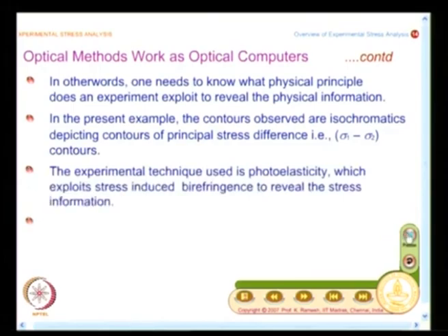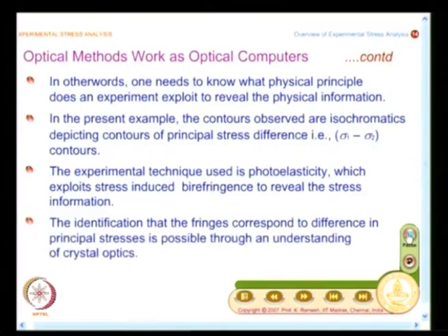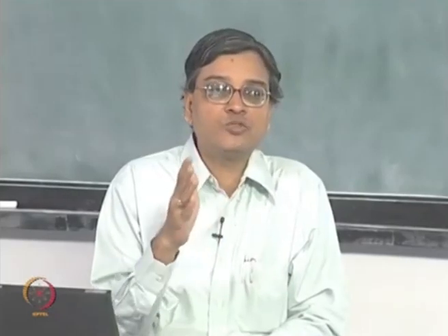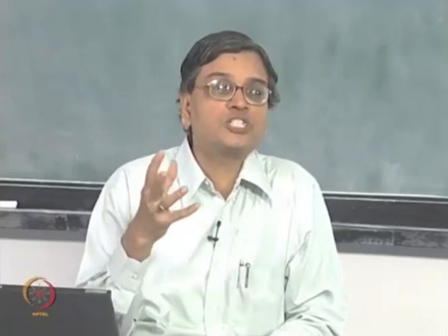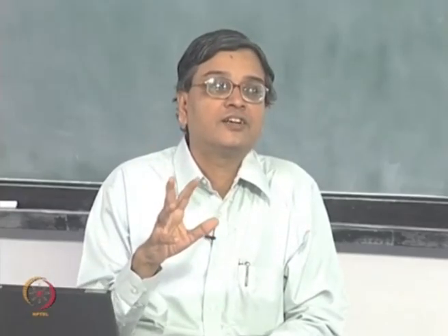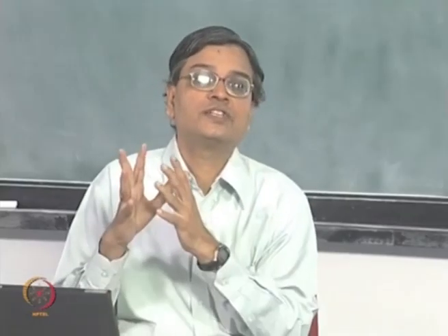And the technique that is used is photoelasticity, which, as I said, exploits stress induced birefringence to reveal the stress information. That is why I have taken a specimen which behaves like a crystal when it is loaded. That is the epoxy, which has the phenomenon of stress induced birefringence, and because stress induces changes in the optics, by analyzing the optics information it is possible for you to relate the effect of optics to stress patterns.